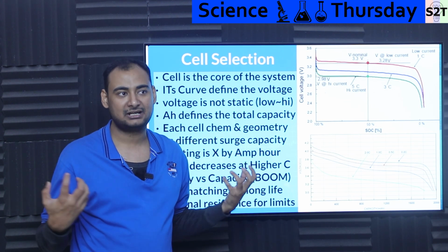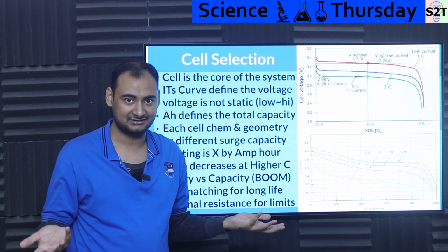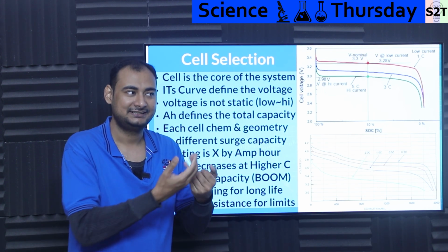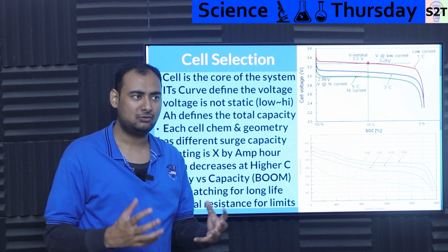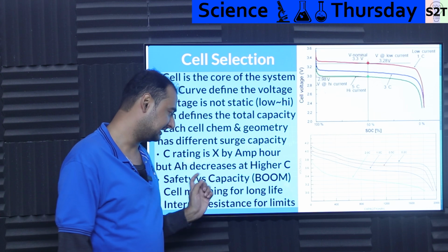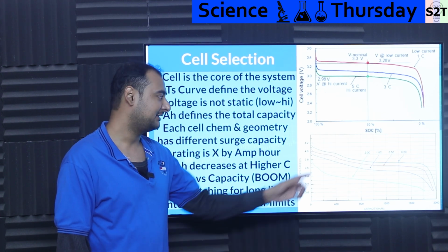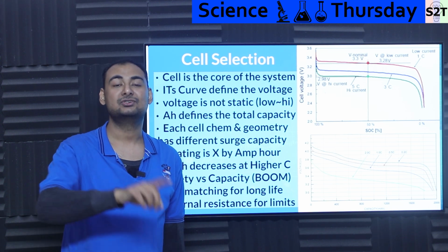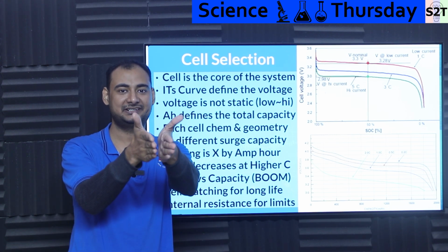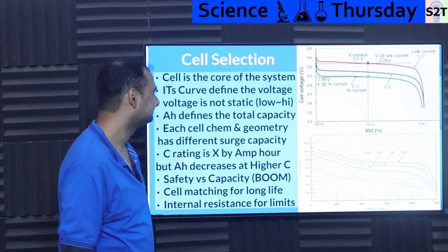like how much oomph you can get out of it. Again, inherently the chemistry can just burn, so it has more than enough oomph. It's just how quickly it can dump it. So internal resistance, like how much short circuit current it can handle, that is generally limited by internal resistance. So that's why you cannot have like 500C. Again, that goes to the capacitor. Why? A capacitor is just flat plates, fundamentally speaking.